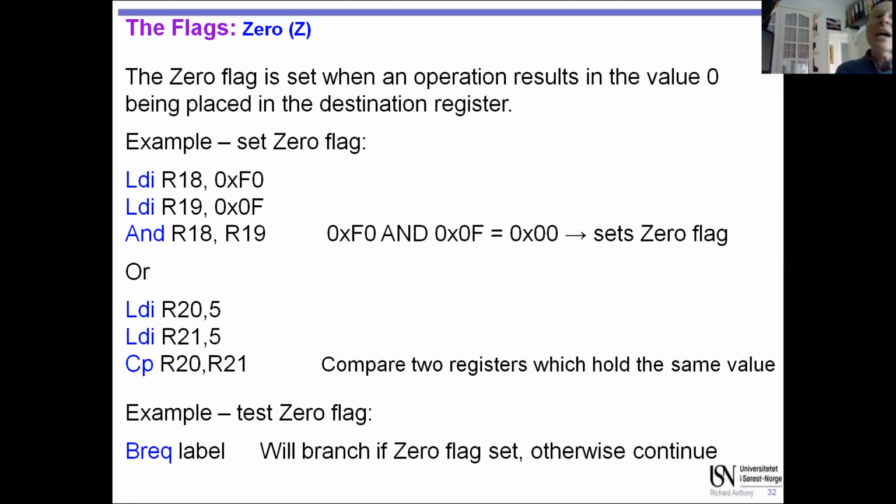So that's simply how it works. It's actually simpler than you first think. It literally says, if this is not 0, just carry on the normal instruction flow. And if the 0 flag is set, move into the program counter this place instead. That's all it does. So it actually demystifies what this branch does. It's actually simpler than many other instructions.